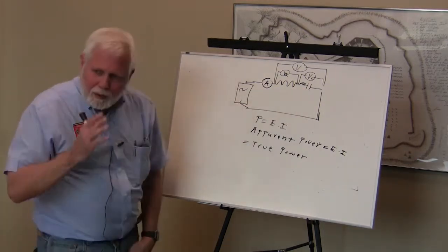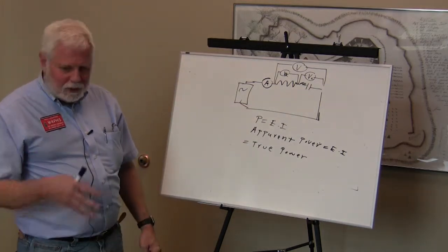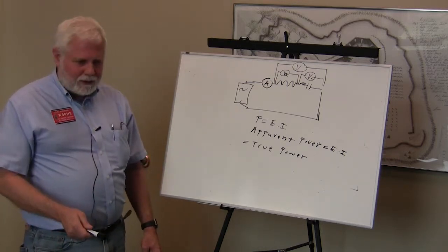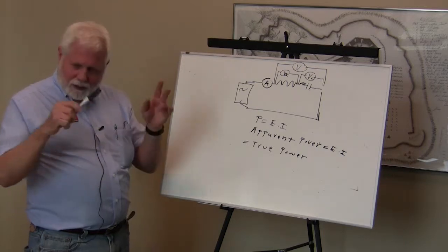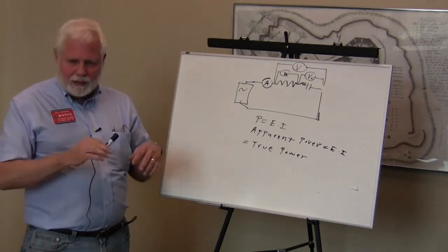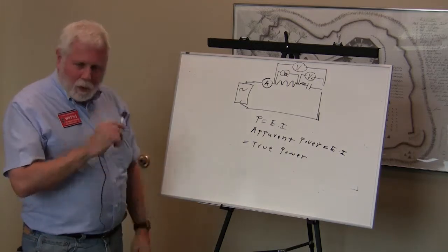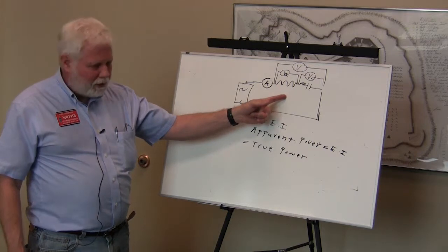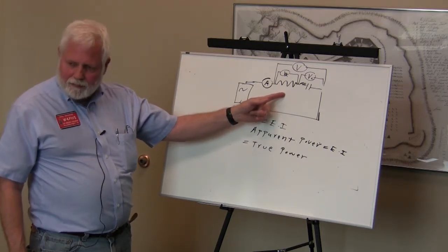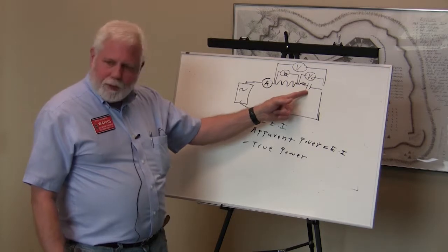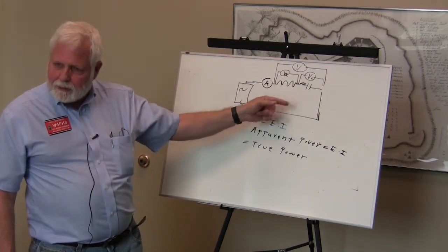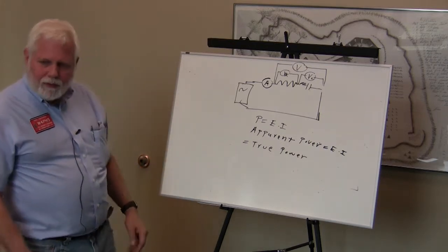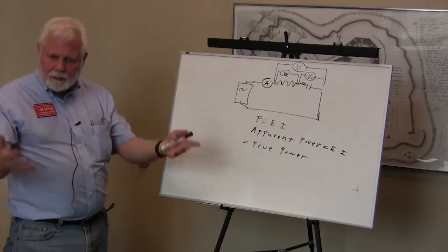Now here's a really important concept, and you can get the answer to some questions by just remembering this. Power is only dissipated by resistors. If you've got a circuit that has resistors and capacitors and inductors, and they say a certain amount of current's flowing through it, whatever current is flowing through the resistor is dissipated as real power. Current through resistors is real power. Current through capacitors and inductors does not dissipate any power at all. It's stored and returned, but not dissipated. So you only have to think about resistors in terms of what is dissipating power.